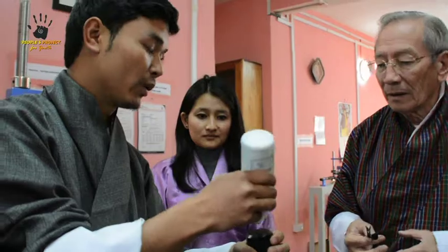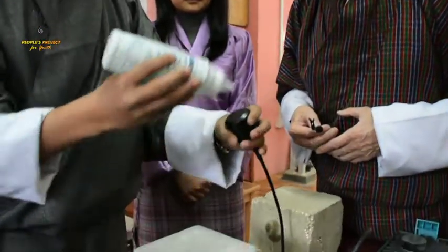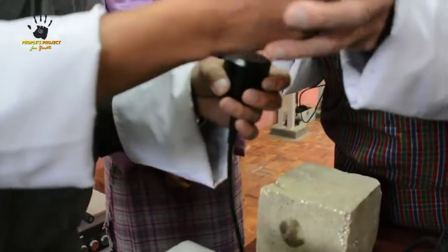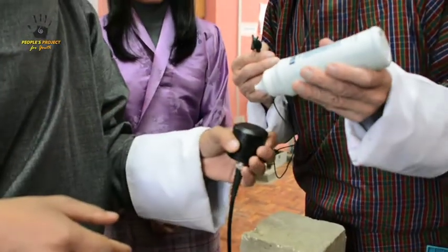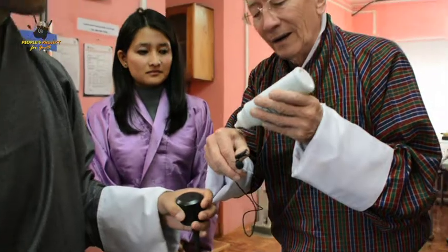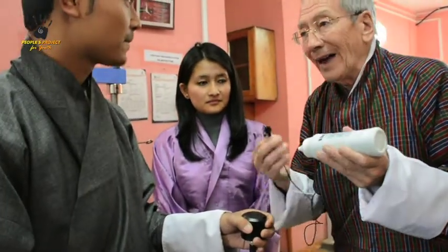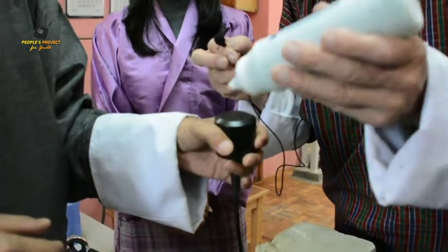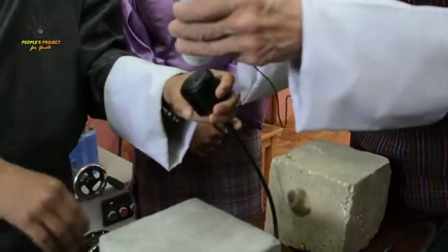Okay. Right, we have this gel. We are providing on the probes, so there will be a good transmission of the sound between the probes. So this is exactly what happens in the hospital, isn't it? If you have an ultrasound, they put a little bit of gel on your skin or on the probe, and that gives a good transmission of the ultrasound waves, which are, remember, very high-frequency sound waves. It gives a good transmission from the probe into your skin. In our case, from the probe into the concrete.